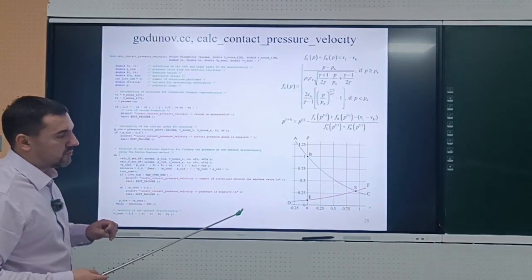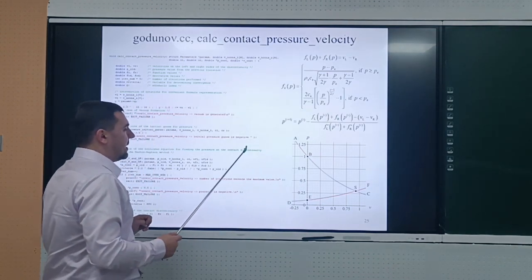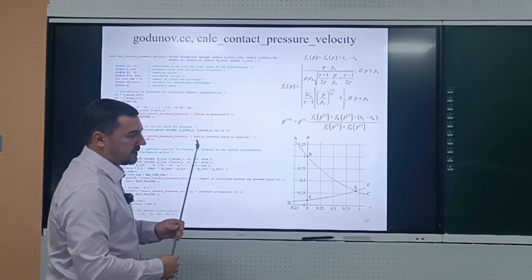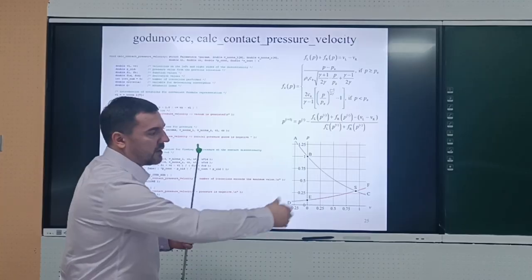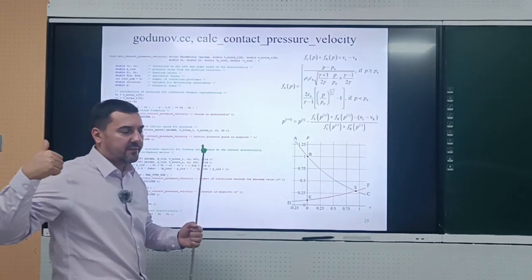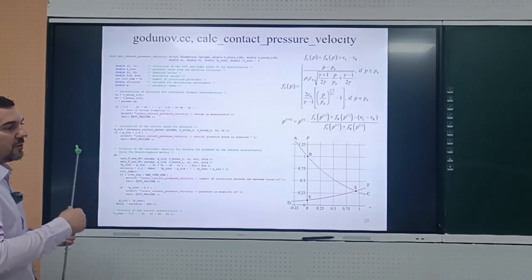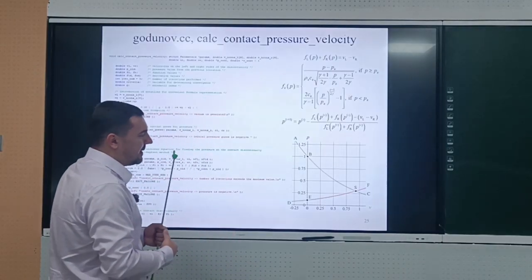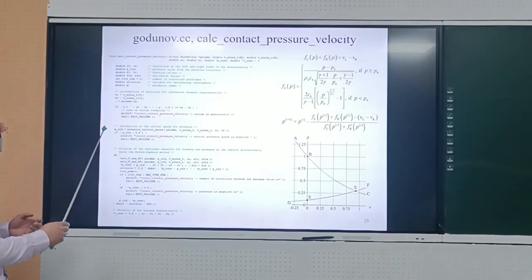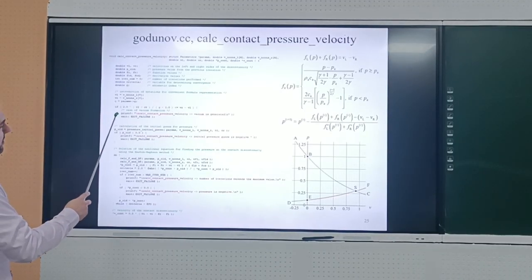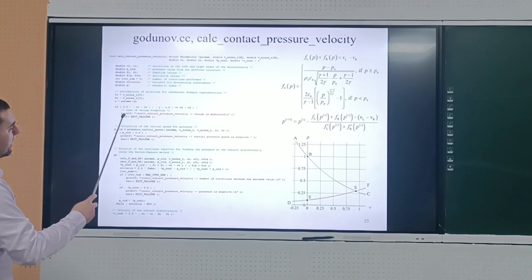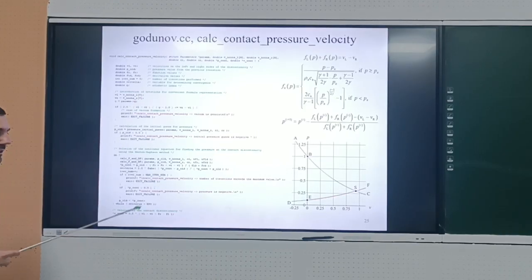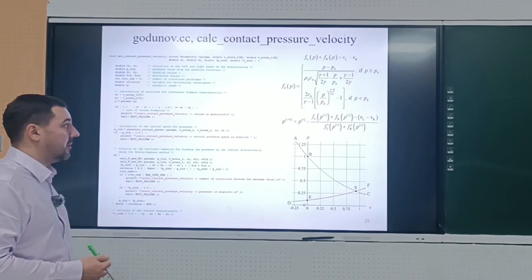we try to use some external parameters. For example, consider that at the initial time instant we provide speed of gas several kilometers per second to the left, and several kilometers per second in the opposite direction. It's not possible for the gas to provide such a type of flow. From a mathematical point of view, this is the so-called case of vacuum formation. So if this condition is not valid, it means that there is no solution of the Riemann problem.